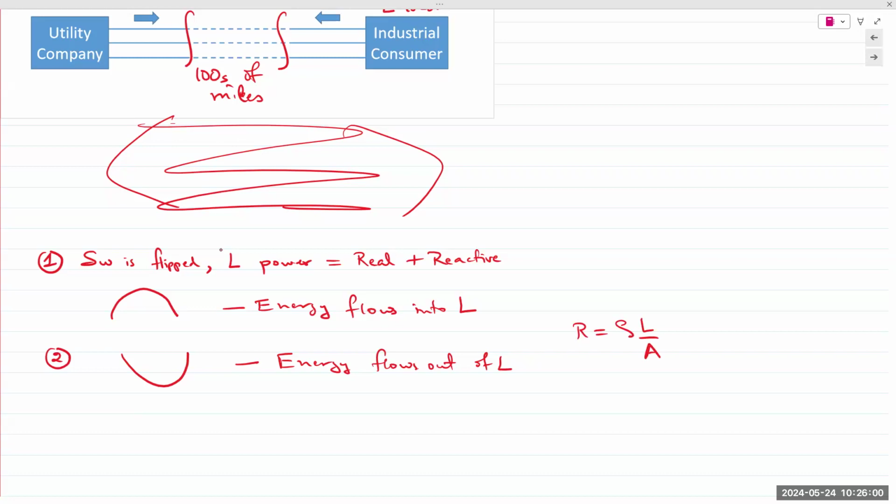So if you take like a 10-foot section of a conductor, long distance transmission lines are like really thick, but in reality, compared to the length, it's small. So even if you take, let's say, a small piece of that miles long conductor, it'll have a resistance of a few ohms perhaps. But when it's tens of miles long, that resistance increases. And that resistance of that conducting wire causes transmission losses.